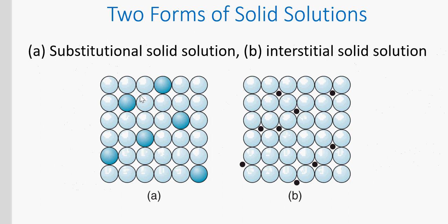While substitutional means, an example is copper and nickel. So the atoms substitute each other. You can see there is 1, 2, 3, 4, 5, 6. Assuming the base metal is copper, then the nickel will come in and substitute. Nickel and copper have similar properties, similar electronegativities, valencies, and also size and density. So they can substitute what? Each other. Substituting each other means it is what? Substitutional. And you cannot see any change. They can easily dissolve in one another, and that's why we call them solid solution. Even this carbon will dissolve in the iron, and it's called solid solution.